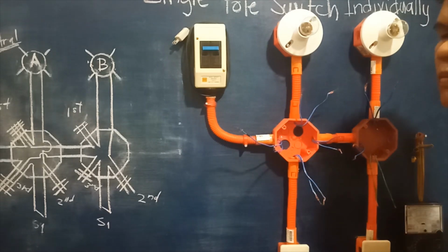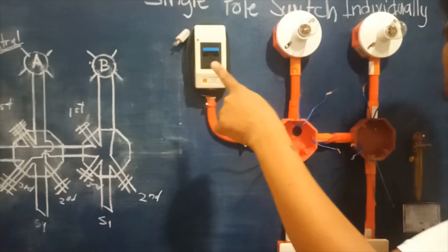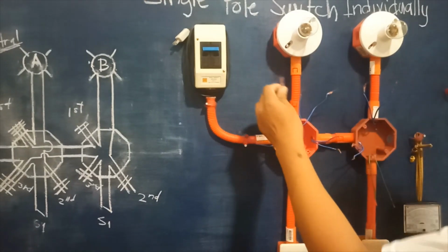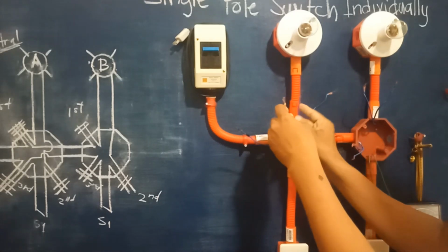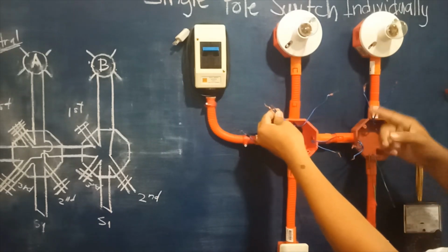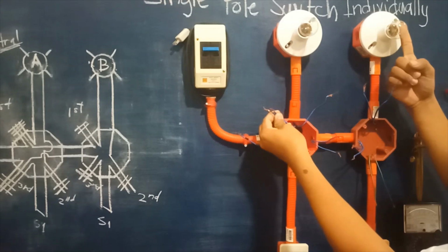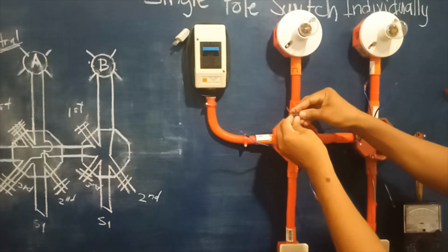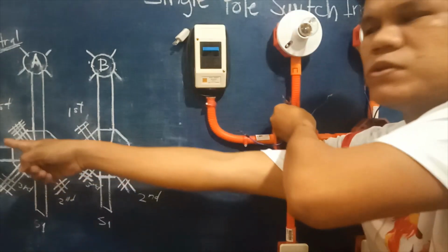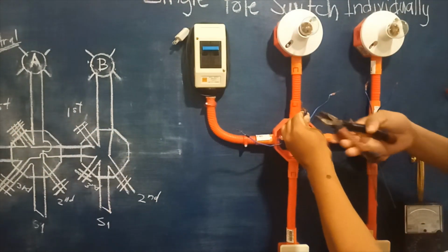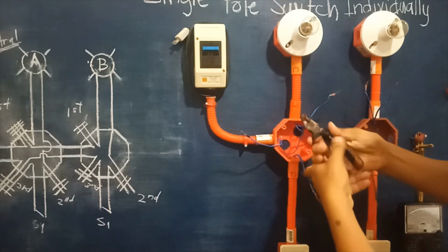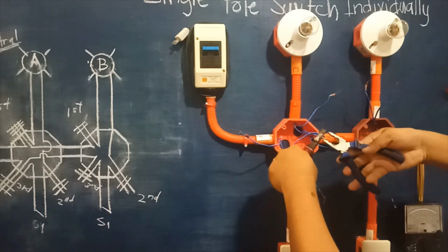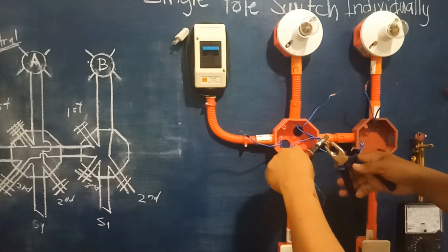So in the first cycle, take note, we have from the source, which is line 1, going to the load. So neutrals coming from source to load, this one. And of course, we will supply the other wires coming from our second bulb. So we will use this wire. So 3 wires already. So 3 wires also right there in our diagram. So do this one. So 3 wires connected together here in the first cycle on the first branch of our circuit.